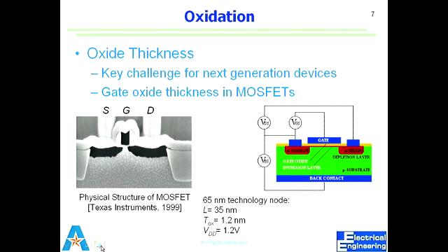It can be the gate length also. So ITRS defines the node based on the smallest feature size in a given technology that is being made. Right? So in 65 nanometer, the length of channel is 35 nanometer, oxide thickness is 1.2 nanometer, and drain voltage is 1.2 volts.